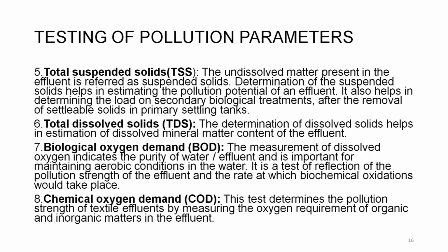It also helps in determining the load on secondary biological treatments after the removal of settleable solids in primary settling tanks. So, this is also important because all the suspended solids are the ones which create the turbidity, and if it is a very turbid solution, then we know that the sunlight cannot penetrate through that. So, the aquatic life gets disrupted.